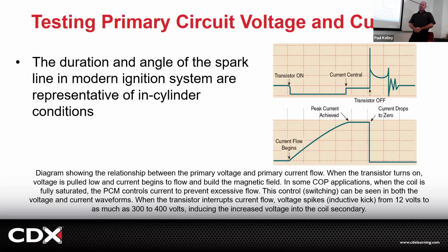But the ASE does ask some of these questions. And I've always been a little soft on it because I read about it, I learned about it, but I would not commonly be hooking up an oscilloscope and measuring these waveforms to do an ignition misfire diagnosis. You know what I'd be doing? Checking for spark, switching the coil, measuring the voltage of the primary, but I don't necessarily normally need to see this whole diagram.